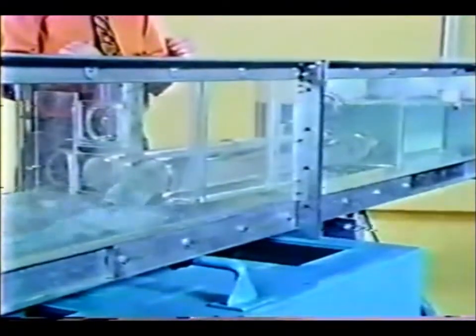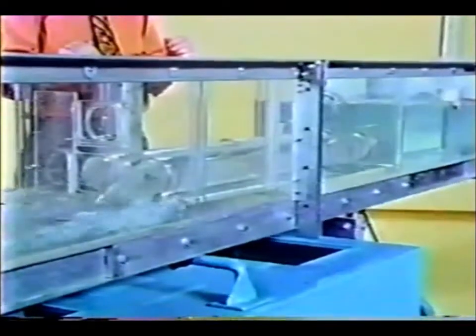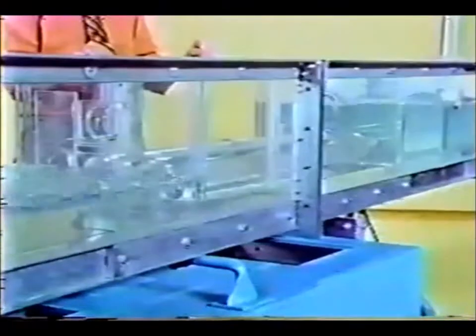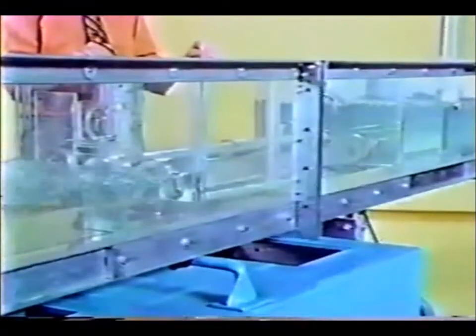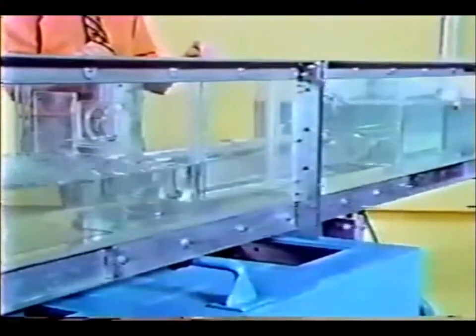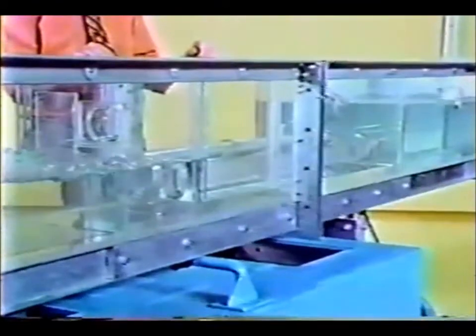When the culvert is operating with low tailwater, the flow is plunging through critical depth near the outlet. Therefore, critical depth is controlling the outlet velocity, and the headwater pool reflects only those factors upstream from the outlet. As the tailwater elevation is raised, the headwater pool elevation remains constant as long as critical depth controls. However, there is a point where the tailwater drowns out critical depth. Above this point, the headwater and tailwater rise at the same rate.